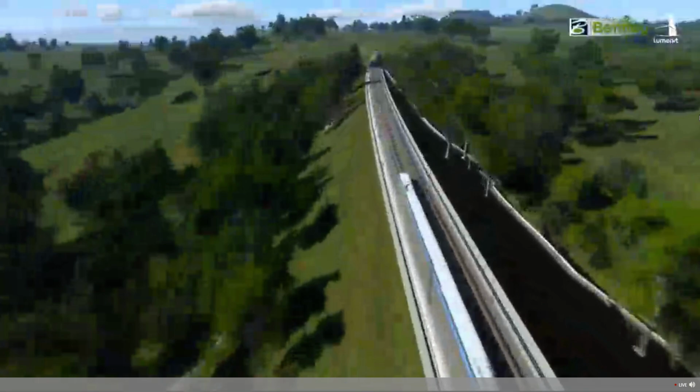So if you need to take in the geometry to OpenRoads Designer, you can output that into LandXML or maybe an ALG format. The terrain as well, you can output into DTM, making sure that whatever you have created in the conceptual model can also be taken to the detailed design aspect.